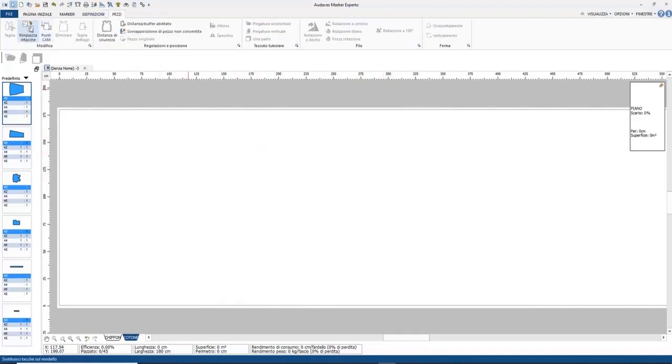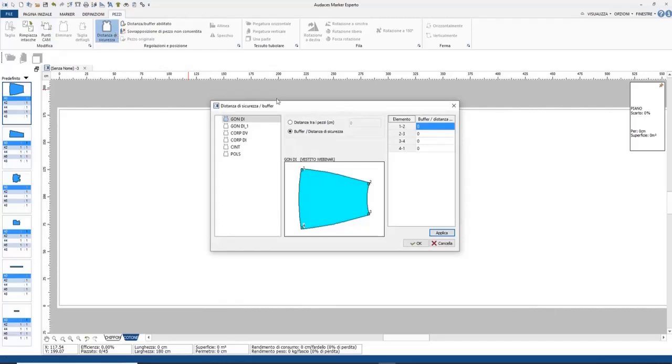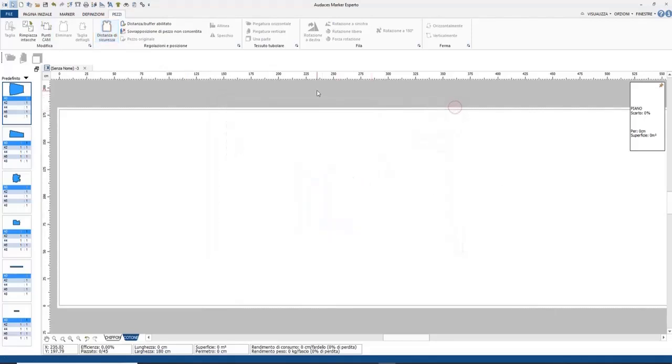In the Pattern tab, we can replace the notches and decide the position of the cam points. These are points from where the cutting machine starts to cut the fabric. The security distance, that normally is always enabled, adds a margin on the contour of the pieces to avoid overlapping.